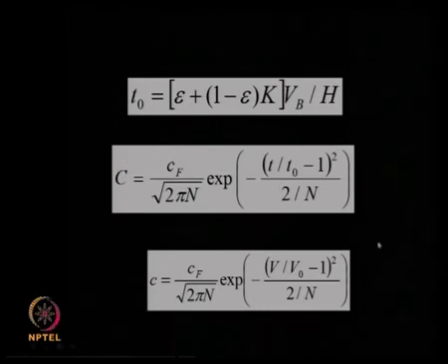So these two equations are very useful. Here we have the number of theoretical stages, we have the feed concentrations, we have the elution time coming into the picture, and here we have the concentration coming on the left hand side. So these equations again can be used for design calculations, as we are going to see in some more problems as we go along.